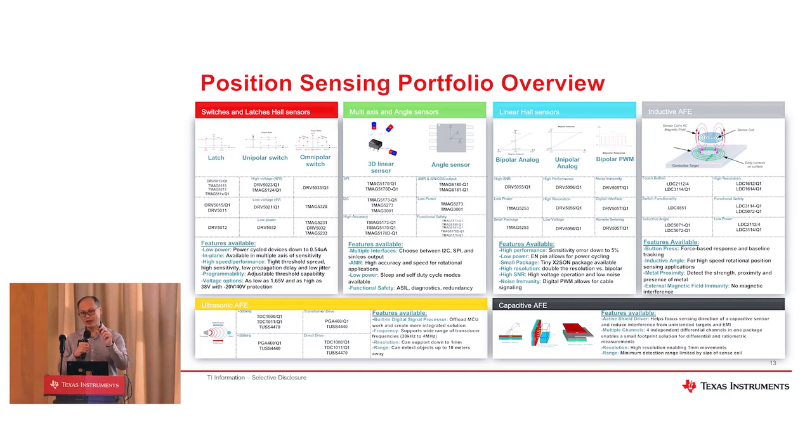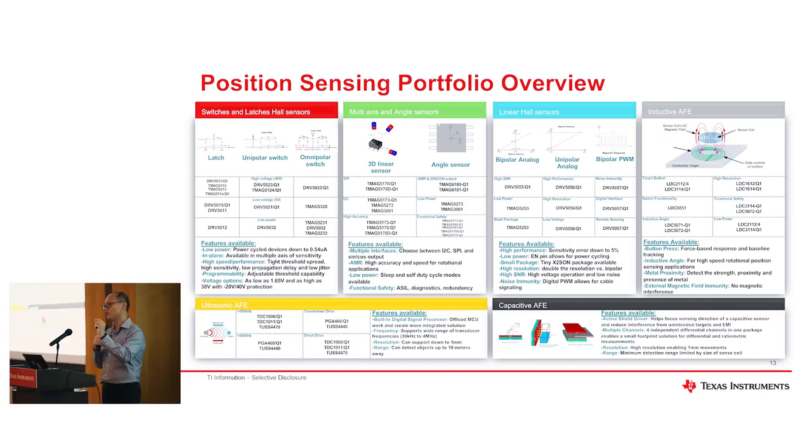One other way to detect so-called materials or metals is inductive sensing. This one uses a dynamic magnetic field to detect a metal. So this is good for very advanced applications, such as detecting whether a coin is real or fake. You can detect the material composition, how many percent copper, how many percent aluminium, through this inductive sensing. So it's an inductive AFE for very advanced material detection. It's not just on and off, not just linear, but detecting the differences in the materials.